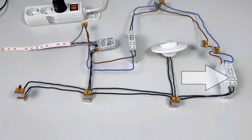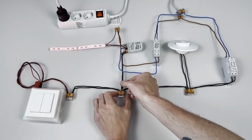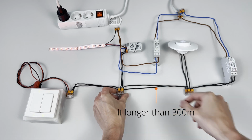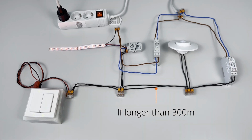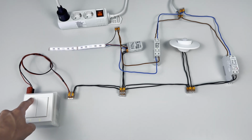Pressing the test button will not trigger any response from the dimmers, as no communication can occur on a shorted bus. If wiring is intact, but the cable length is too long, or the wire cross-section is too small, an excessive voltage drop may occur. In such cases, devices furthest away from the power supply are most likely to fail first.